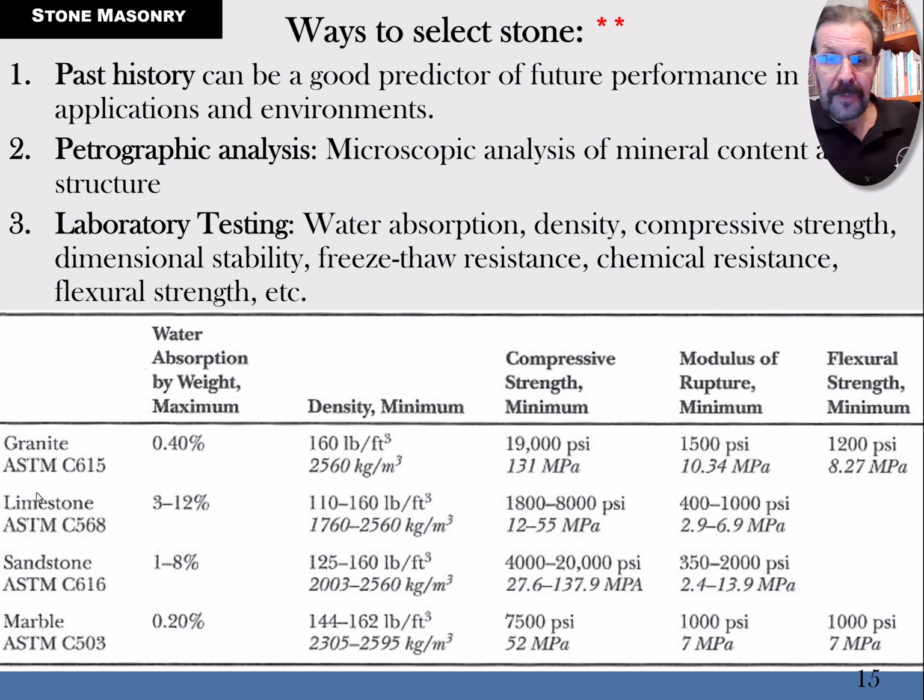So when it comes to compressive strength, the granite is kind of the king, consistent king anyways, much, much stronger than concrete, or most concrete. There are some advanced, super high strength concrete, what we call ultra high strength concrete, that could be in that neighborhood of 19,000 or 20,000 pounds. But most concrete is going to be somewhere around 4,000, unless you got high strength concrete for bridge girders and stuff. They might be in the 6,000 or 7,000 psi mostly.